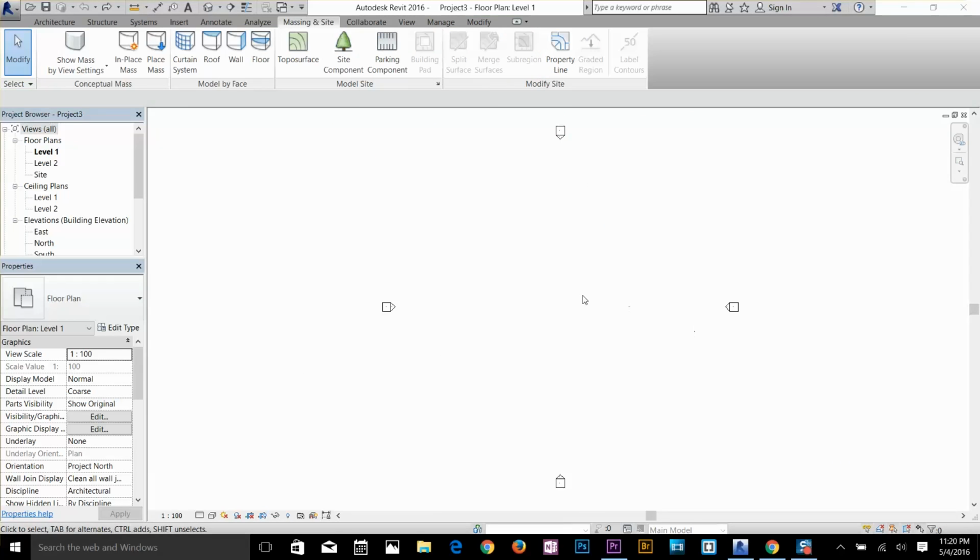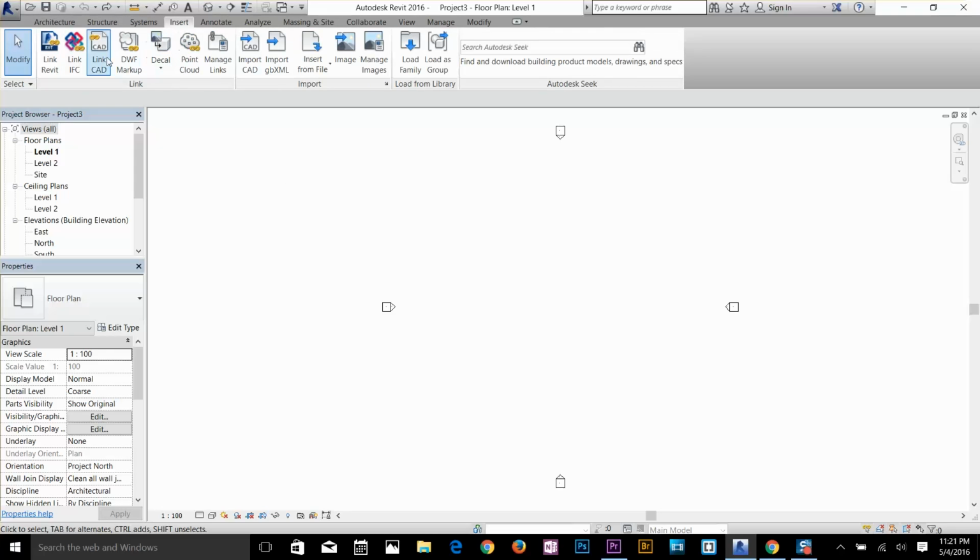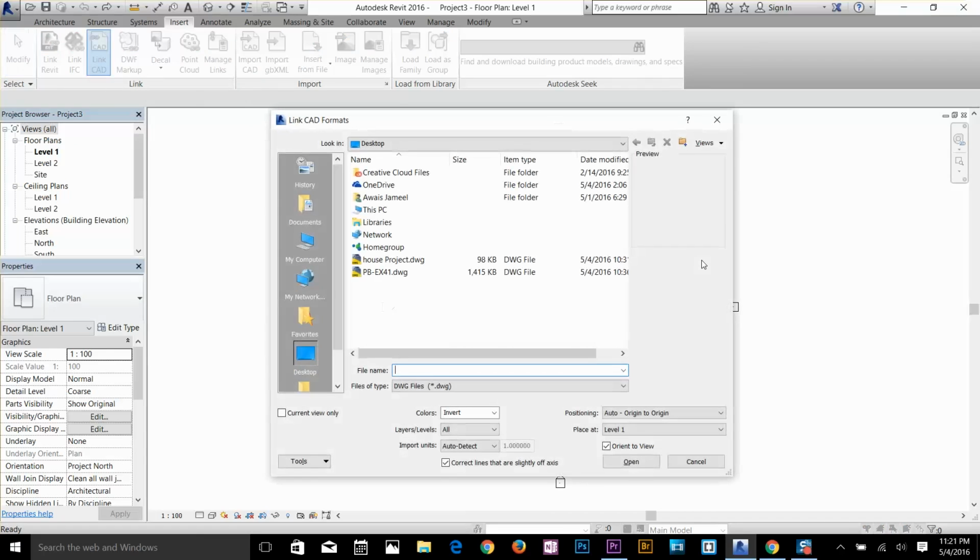I'm gonna look at another scenario you might have to do. You might have to bring some CAD data, like creating topography from a DWG link. So you might get some files from outside, the civil engineer. So there is no actual package for Revit to make a contour file. So what I want to do, I want to go and click on my Insert tab and I'm gonna click on Link CAD. And I've got another file here. It ships with AutoCAD as a sample file.